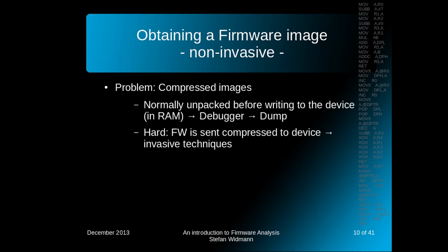One challenge that awaits us is that maybe the updaters contain compressed images. They are normally unpacked before the image is written to the device. So we can just watch the process memory of the process with the debugger, and we dump it. What is a little bit more challenging is when the firmware is sent compressed to the device. So we have to use invasive techniques we will be talking about later.